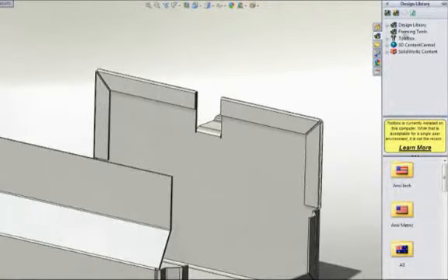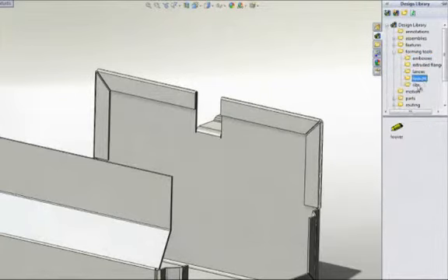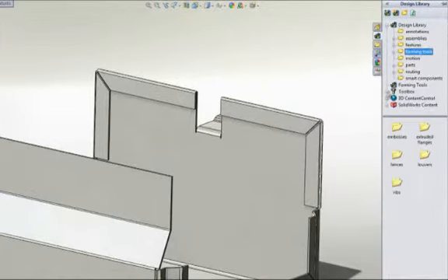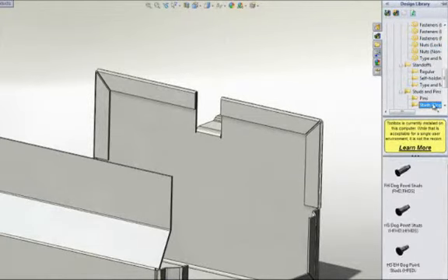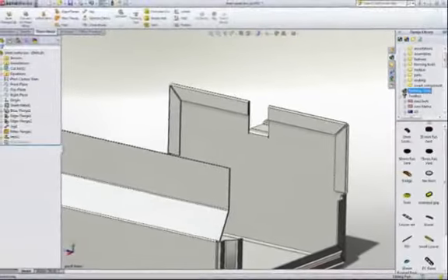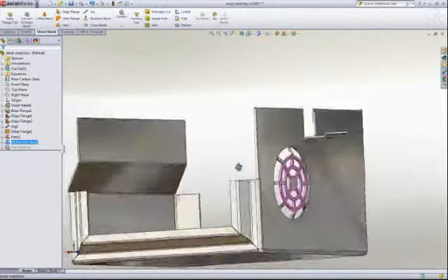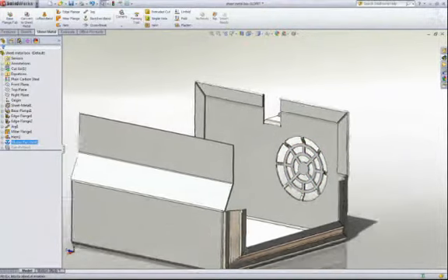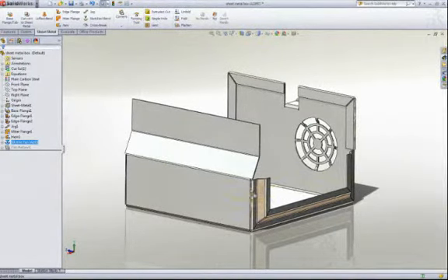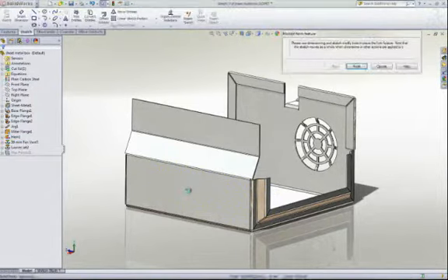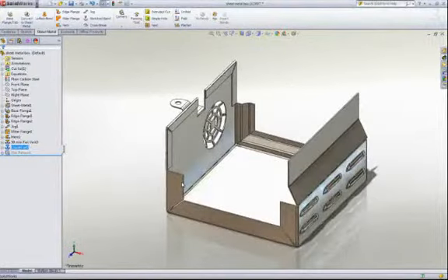SolidWorks comes with a customizable library of pre-configured forming tools, such as embosses, lances, louvers, and ribs. The library also contains many common sheet metal fasteners like PEM nuts, standoffs, and studs. Custom libraries can be created to match your in-house tooling and are applied to the part with a simple drag and drop. As we add this louver set, it's easy to see and toggle which side of the tool is struck. Material is deformed and lanced as defined by our standard form tool.